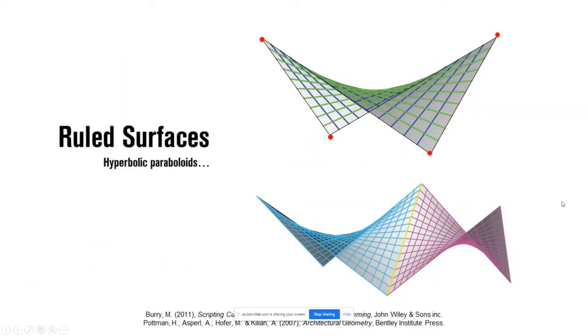I'm assuming most of the audience knows what a ruled surface is, but it's a form of hyperbolic paraboloid that can be described with straight lines. That's what makes it quite simple to form these doubly curved shapes. It's a negative curvature or anticlastic curvature. The great thing about this geometry is that it's one of the most structurally efficient geometries that you can use,